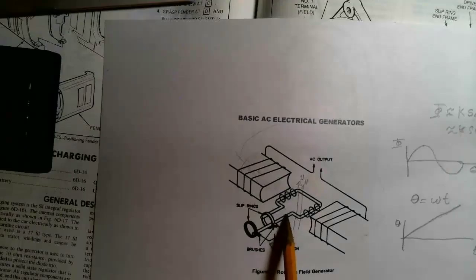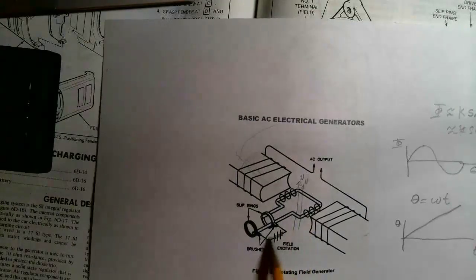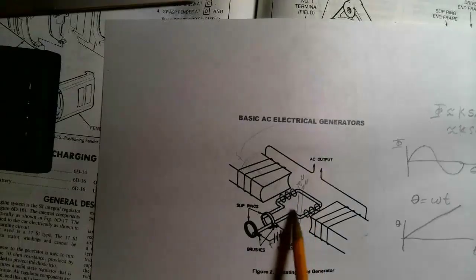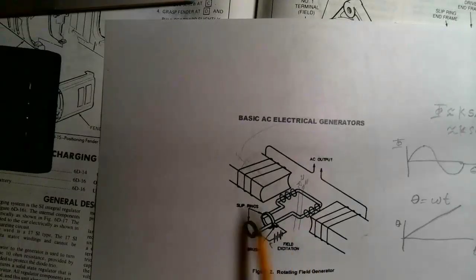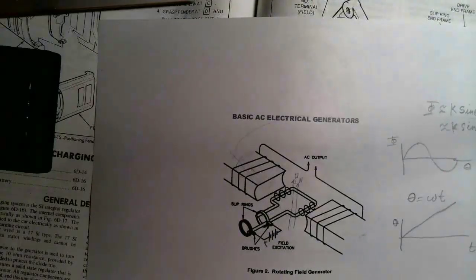So some people a long time ago figured out that to control the output of a generator or AC alternator like this, you can control this rotor current, and then that would allow you to control the output of the machine. And you certainly need to, because it operates over a huge range of RPM, and also, not only that, a huge range of load. The amount of current the alternator needs to put out can vary from maybe 10 amps to 100 amps pretty easily, just under different operating conditions.